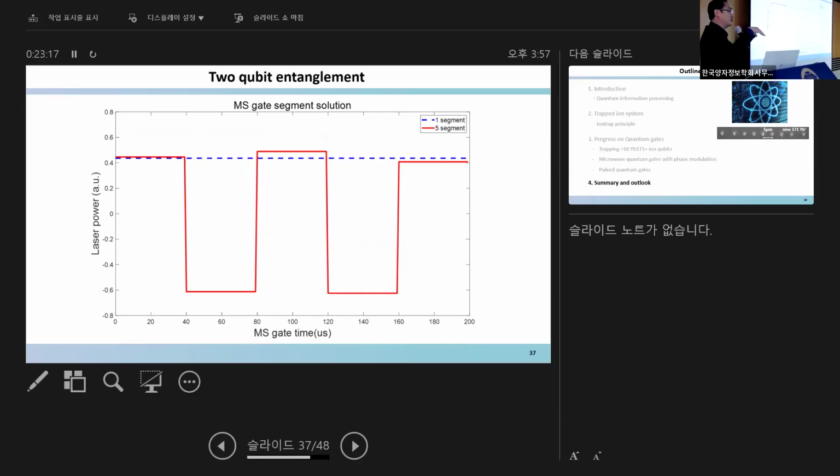And minus laser power means your phase is flipped by 180 degrees. So we can flip the phase of the sine wave by 180 degrees by applying RF with the phase off, then we can make the minus sign. How do we find the optimal phase shape? We can measure through the scope directly. You basically keep controlling, fine tuning to maximize. That's right. So we have a real-time monitor with the oscilloscope as well as the data. We optimize the phase shift.